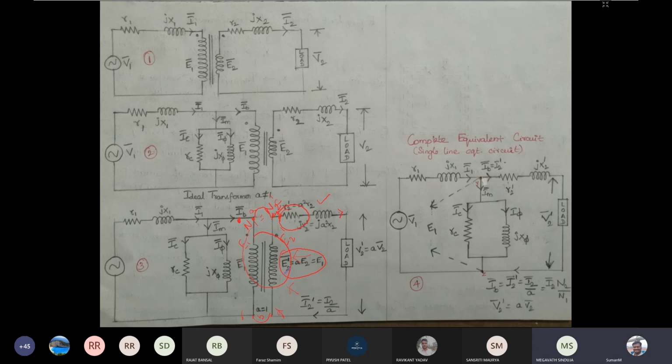So our basic necessity is, before the modification, there is some loss in the system. Thus, that loss should be maintained constant after the modification also. Okay, then only the electrical changes are not happening. The copper loss before and after the modification should be the same. Then only you will be making the equivalent circuit properly. Okay, so just like that, we cannot change this circuit. We are changing the circuit by keeping the loss constant.